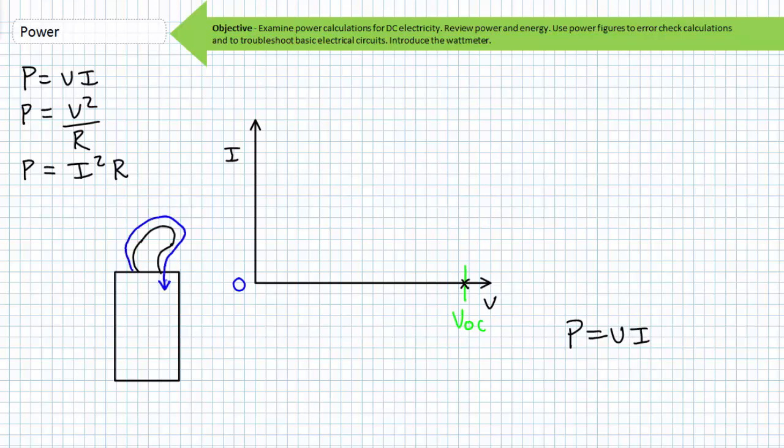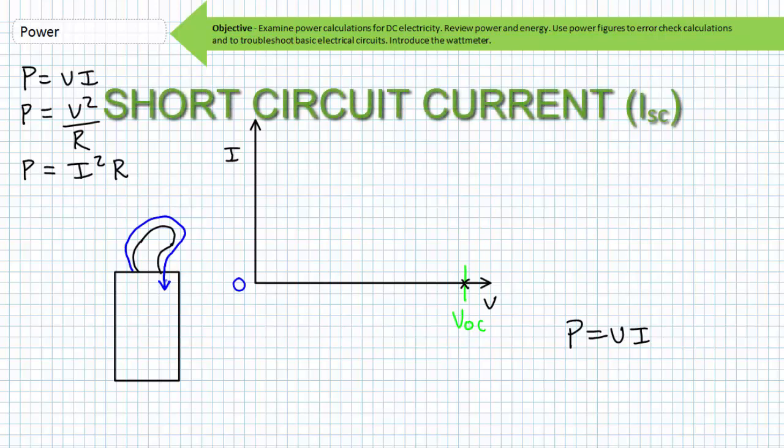Now consider the opposite scenario. Short circuit the two terminals of a PV panel with a 0 ohm resistance path. This is the one occasion you would intentionally short circuit a device because this PV panel is again current limited. Unless you're on a rocket ship and move closer to the sun, there's a certain maximum current this panel could ever produce. But inside the Earth's atmosphere, it will never exceed this current, which is known as the short circuit current, or the ISC.